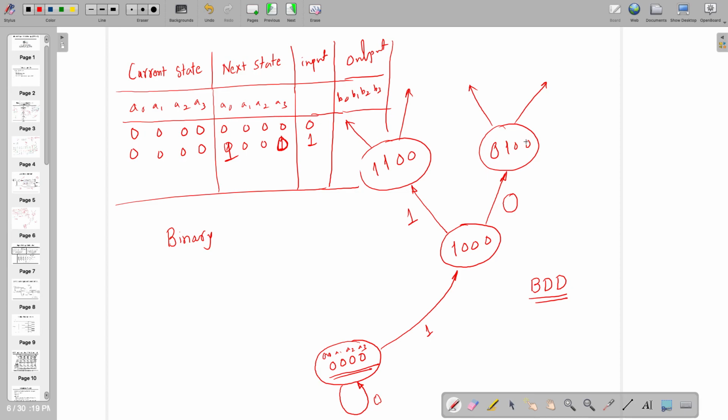That's the main important part. The output is also available with you, but to realize this, if you have four inputs, meaning current state and next state, and you are designing with JK, you are going to have 8 entries, because 4 J entries and 4 K entries.